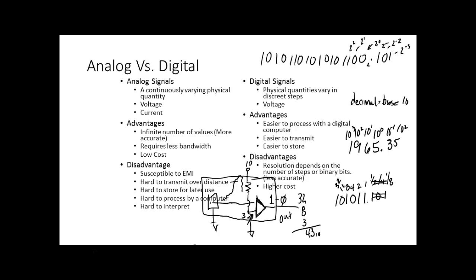You understand that? And a lot of times we'll have a little set screw on it where you can adjust what we call the threshold, where it switches from a true to a false. And that's an A to D converter. But it's a single bit A to D converter, right? You understand? So what am I putting in? I'm putting analog into it, but it's coming back and giving me a true or false out.